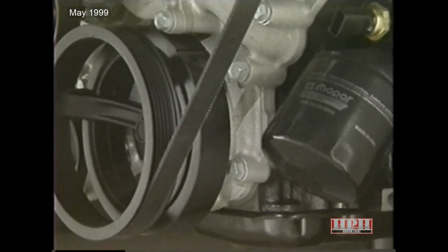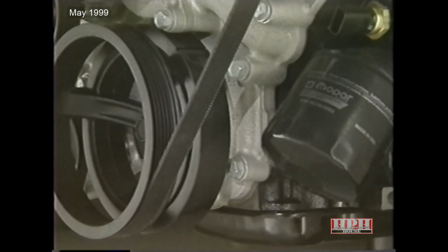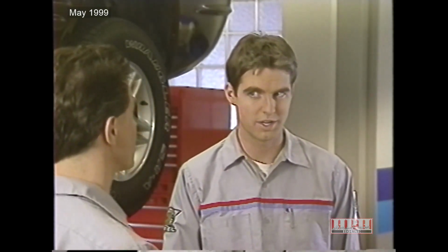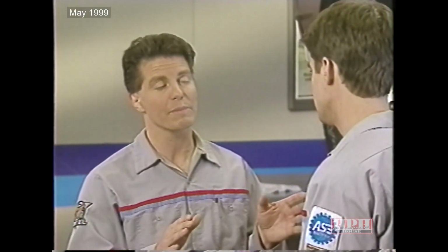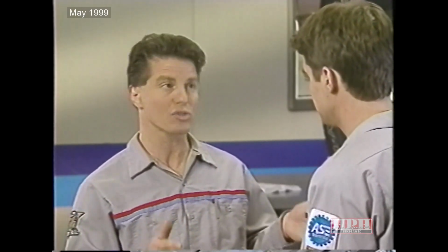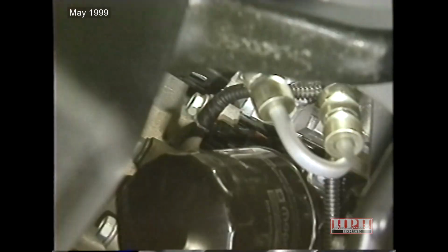Look for oil around the crankshaft front oil seal area. If there was evidence of oil, the seal may need to be replaced. Which isn't a simple task, right? It may take a little bit of time, but having the right tools and following the appropriate service procedures will help. Well, what else should we check?